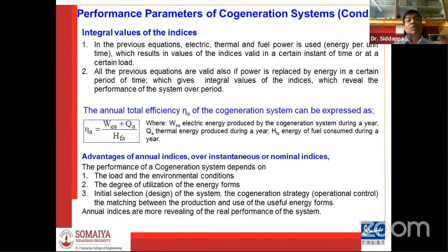Then I have to pump secondary air at a high pressure. Then I have to optimize whether pumping secondary air at higher temperature will be costlier, or taking cold air at a lower temperature, such that getting denser air is more economical. That means I have to check the loading conditions, at what load the system is giving more efficiency, and how environmental conditions play a role. Everything depends upon the values you are measuring.